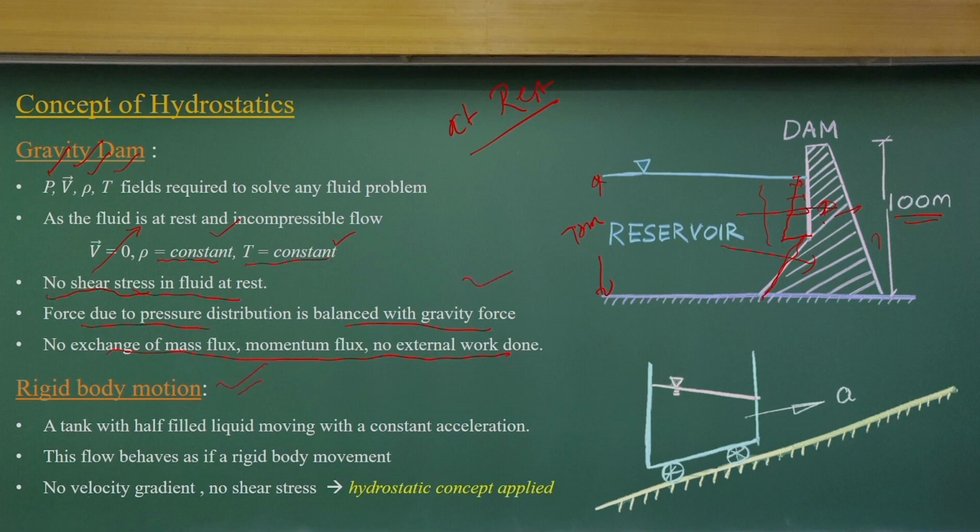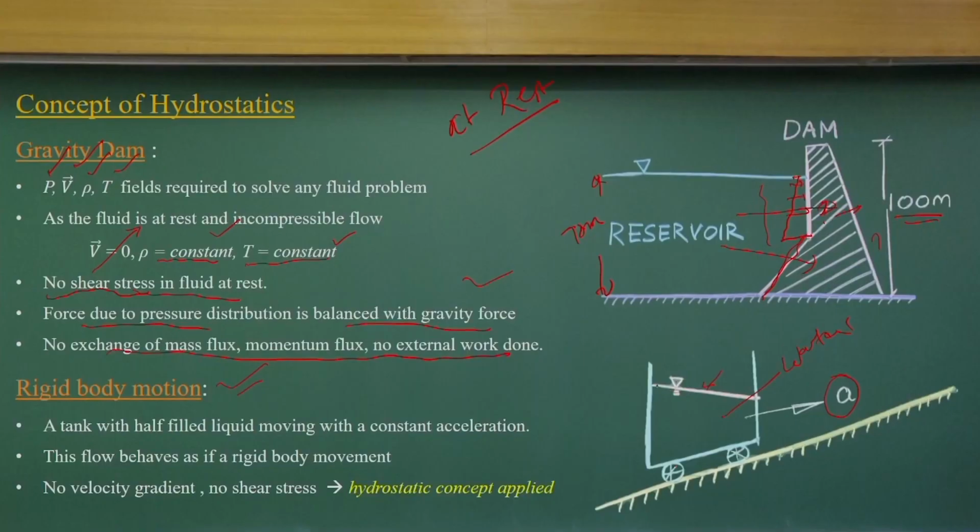The second thing is fluid acting as a rigid body motion. Let us take an example. I have a tank which is half filled with liquid, let us consider water, and this tank is accelerated with a constant acceleration a. As you start accelerating the tank, the free surface is going to change and come to an equilibrium surface, after which the surface will not change.